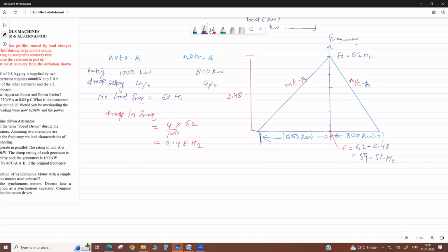Okay, but my dear, total load is only 1000 kilowatt. So see, below this line is not. If we say 2000 kilowatt, if total load is 2000 kilowatt, where do they operate the load? They come from this down. Means slightly they overload. Correct? Both machines are overloaded. So this is your 2000 they can see here. Then this is the characteristic and this will be your frequency. Now this is the 2000 kilowatt, because this plus this is 1800, then they take 100 kilowatt more.